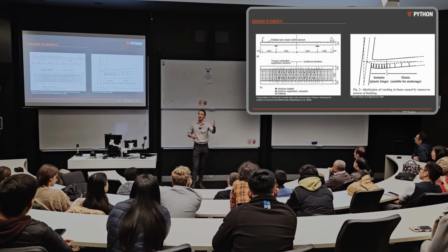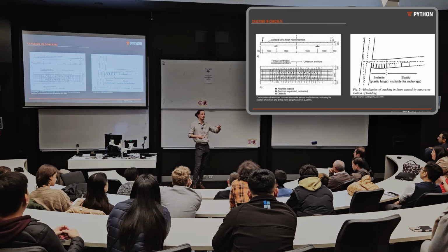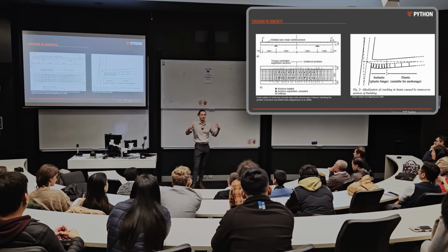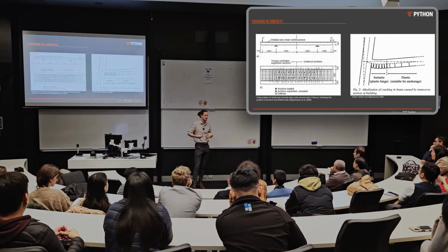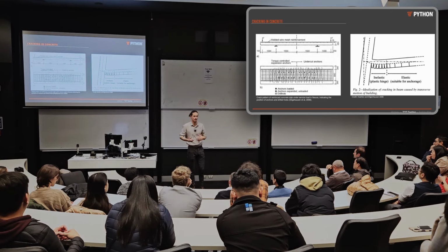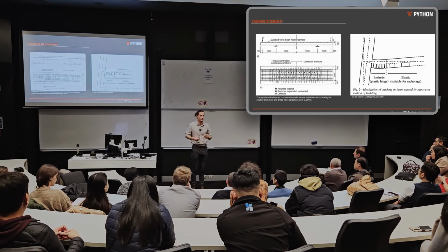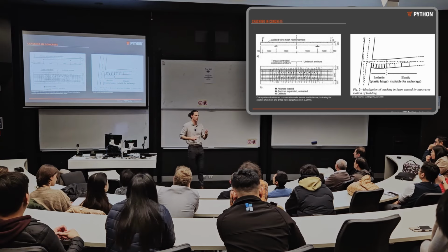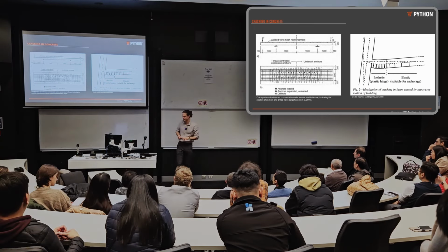The 0.8 crack is meant to represent the scenario where you just start getting yielding of your reinforcing in a concrete beam. And this is meant to represent a high seismic loading scenario. Fundamentally, these are the crack widths we're allowing for. A C2 capacity is allowing for a 0.8 millimeter wide crack.